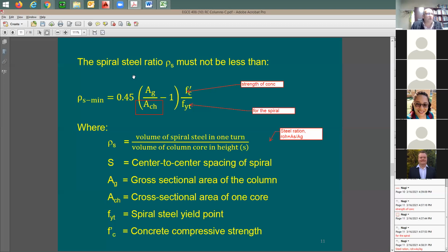How about here in this equation? Does it matter if I use ksi or psi? I believe you'd want to use psi if it's a code equation, that was kind of the advice he gave us, but as long as you're consistent between the two, you should be fine. Here in an equation like this, how about if I have a square root of f'c? Should I use psi or ksi?